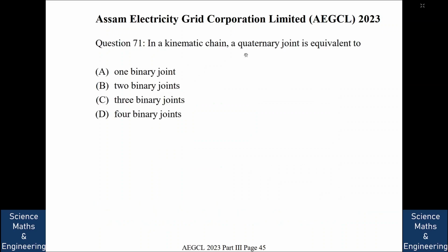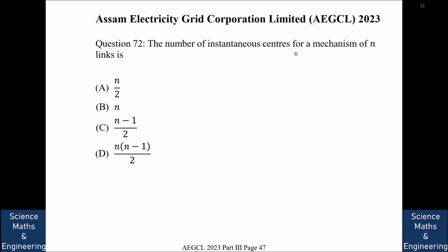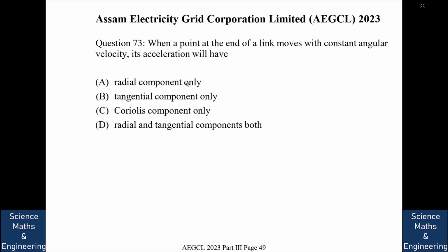In a kinematic chain, a quaternary joint is equivalent to 3 binary joints. Next question. The number of instantaneous centers for a mechanism of n links is n into (n minus 1) by 2. Next question. When a point at the end of a link moves with constant angular velocity, its acceleration will have...